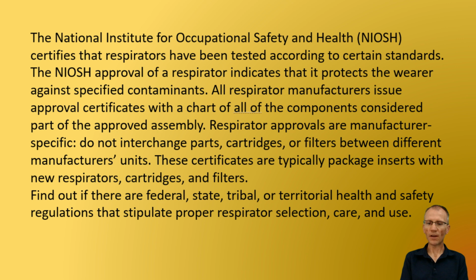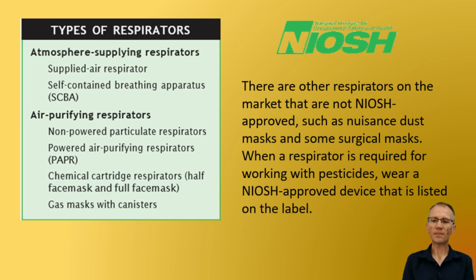Find out if there are federal, state, tribal, or territorial health and safety regulations that stipulate proper respirator selection, care, and use. There are other respirators on the market that are not NIOSH approved, such as nuisance dust masks and some surgical masks. When a respirator is required for working with pesticides, wear a NIOSH approved device that is listed on the label.